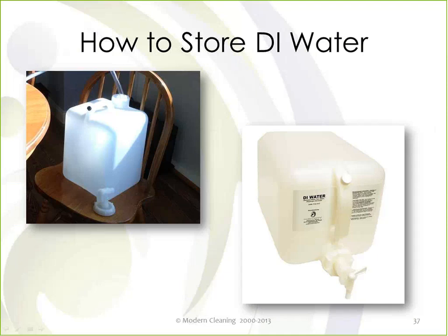Again, here's a picture of the buddy jug. Here's a picture of what the jug looks like, and we have a DI water label on this, and off to the right are instructions and precautions, explaining what it is, how to use it, and what to do and not to do with it. One of the things we've been doing is to flush it out every week and flush out the bottles just to prevent the possibility of things starting to grow in there and have water getting stagnant.